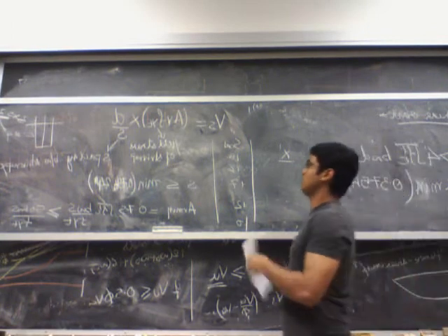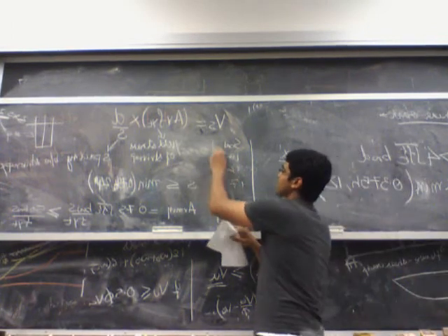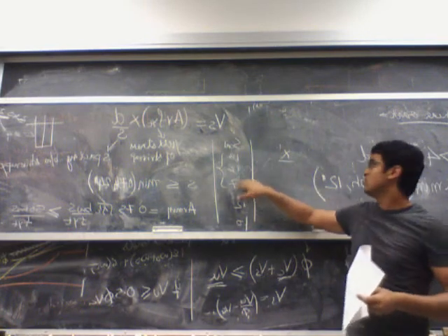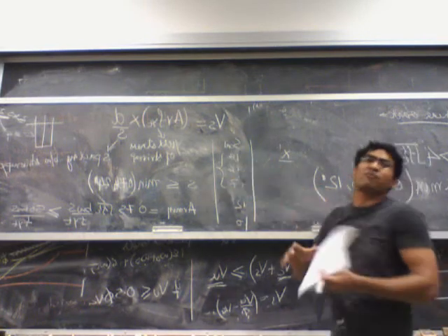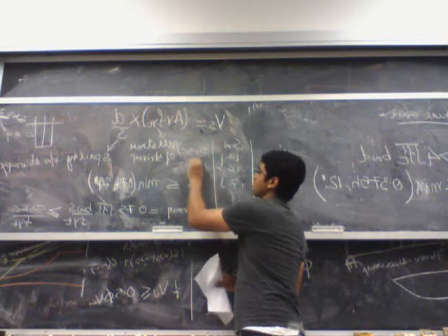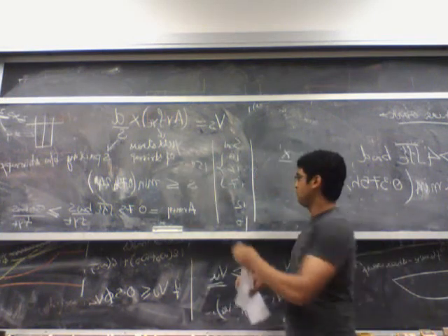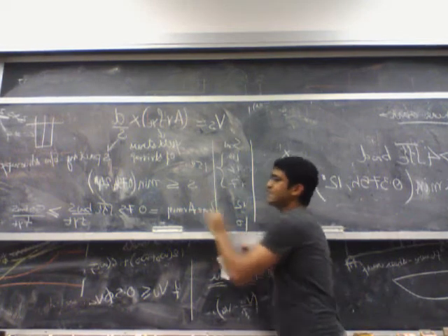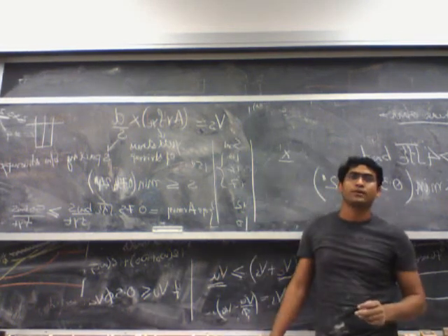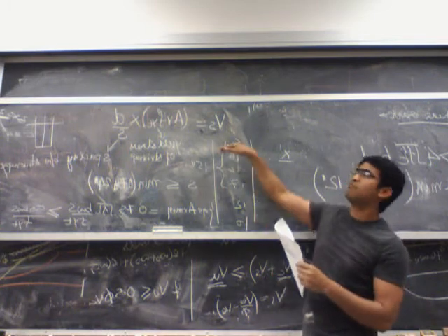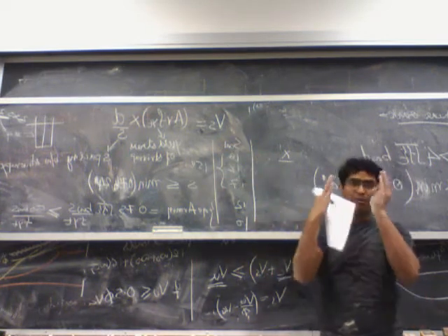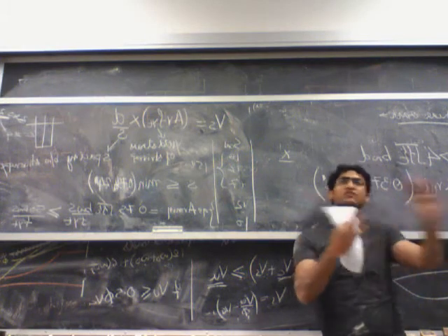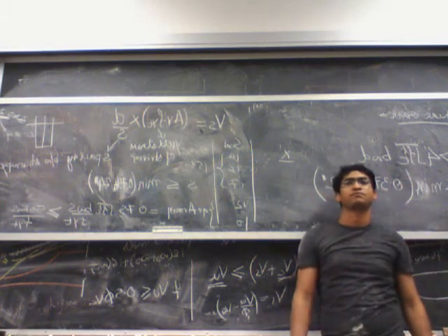So what generally we do is for a certain length, we'll provide a spacing which will satisfy all of them. So within this length, the minimum is 16, I'll provide 15. Then beyond this, it's 12 and 10, so within this I'll provide, let's say, 9 inches or 10 inches. So once you have the calculated required, you break it into sections, and in each section you provide one spacing which will satisfy the entire section.